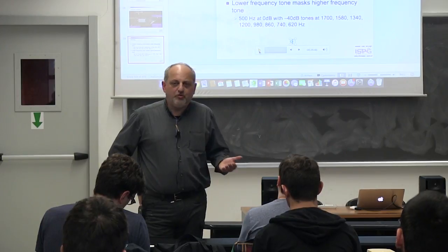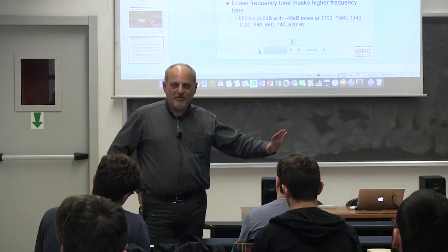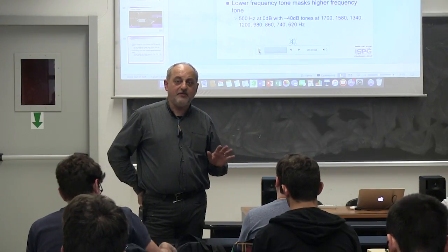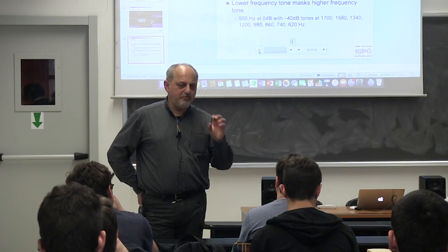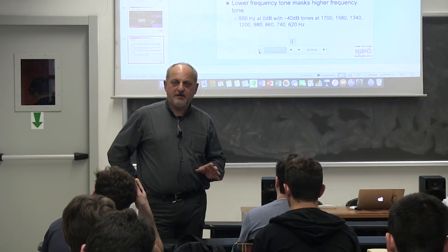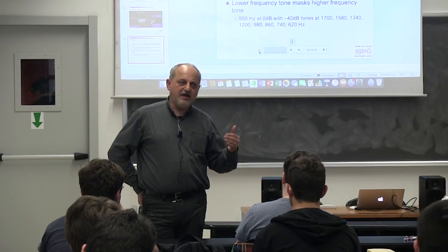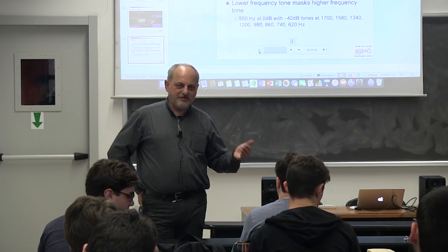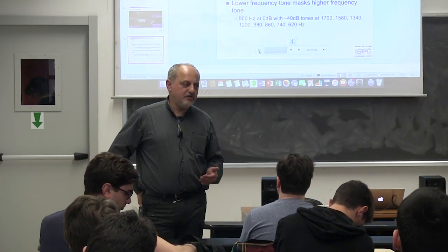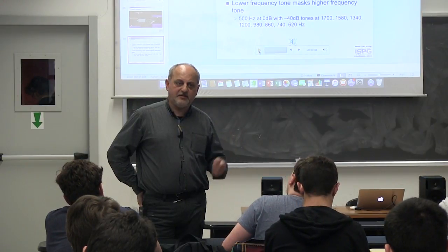And I'm talking about an order of magnitude of compression. I'm not arguing, and I'm not talking about the quality of the result. I'm just telling you that if you tried in any other way other than perceptual encoding, something that exploits the weaknesses in your perception, you would get worse results. I can guarantee you that. So all the theory of encoding, decoding, perceptual encoding and decoding, which are the most effective solutions today for packing more information in the same amount of space, are actually based on exploiting such principles.